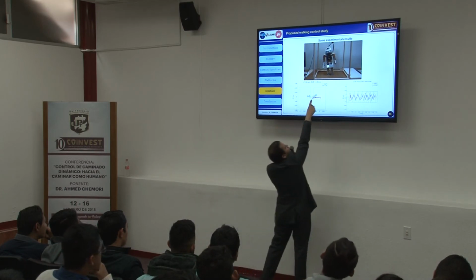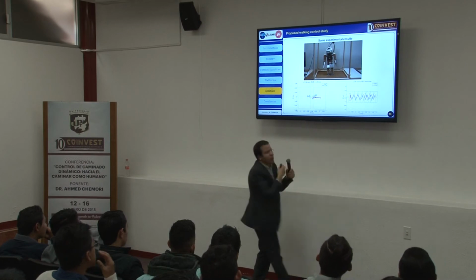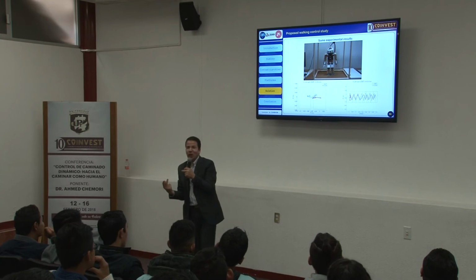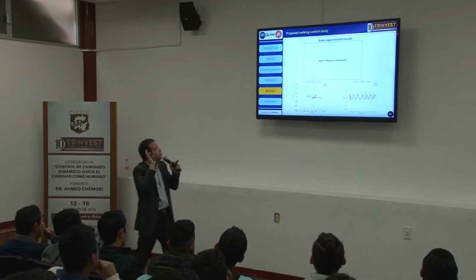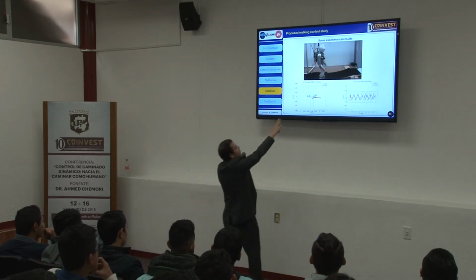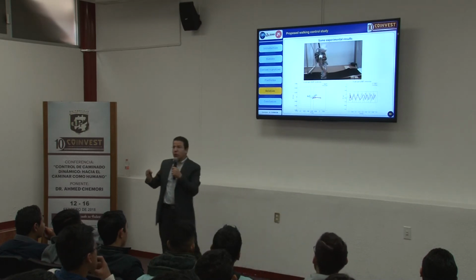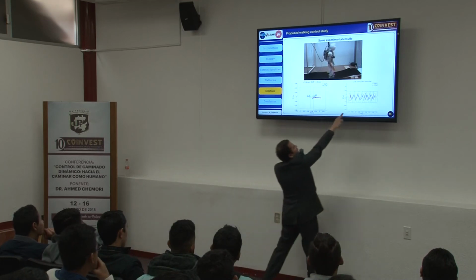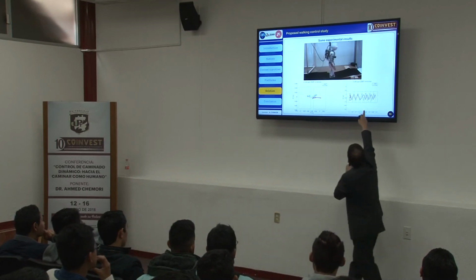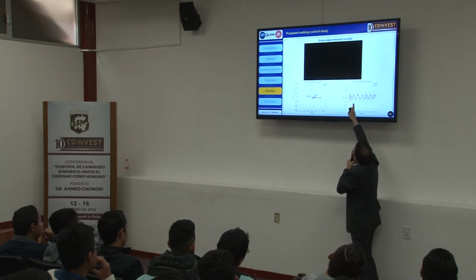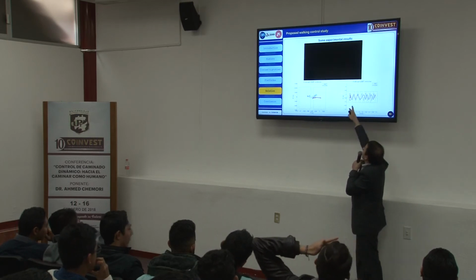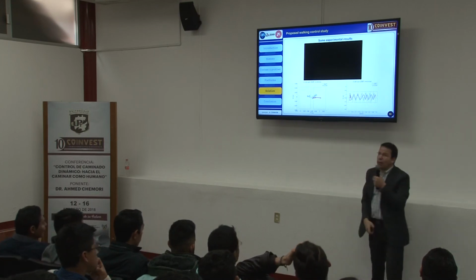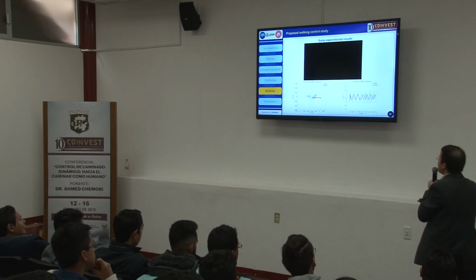Second scenario, we try to pull. There is a wire here, attached here. We try to pull the robot, and the robot will resist to avoid falling down. And automatically, we just have to keep the ZMP inside. And the third scenario, we try to reproduce the human walking on a slope. So we introduce this slope, and as you can see here, you can see the effect of the slope. At the beginning, it's okay. The ZMP and central mass are in phase, but in the end, there is a phase lag between the central mass and the ZMP, because there is this slope.